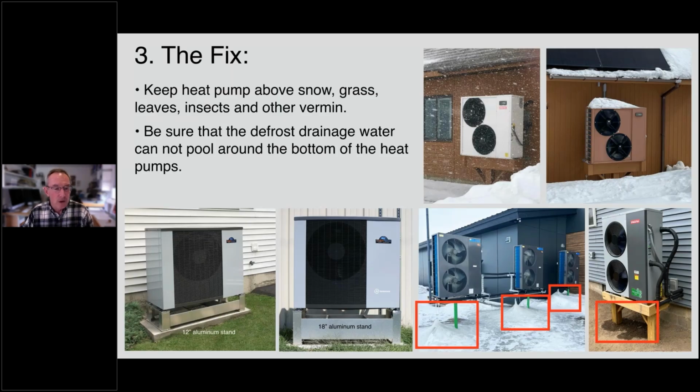Over here in the lower left, you can see a couple of the Intertech outdoor units. Intertech does have a 12-inch stand. They also make an 18-inch stand that can suffice in many locations. Another thing to think about is the condensate drainage coming out during defrost. During defrost, these heat pumps can drop easily a quart, maybe even sometimes a little more than a quart of water.